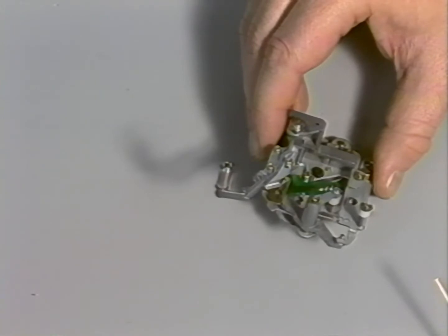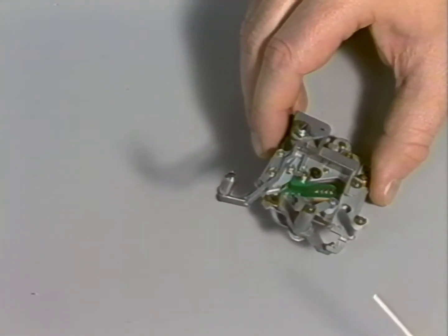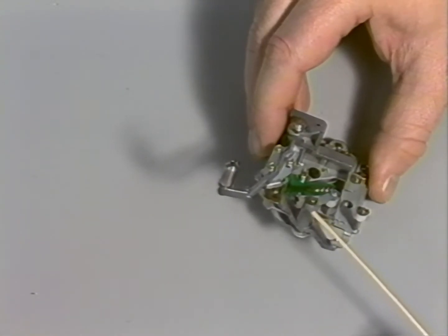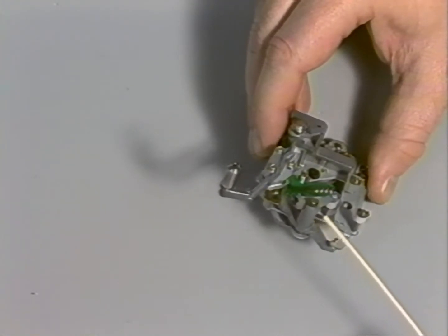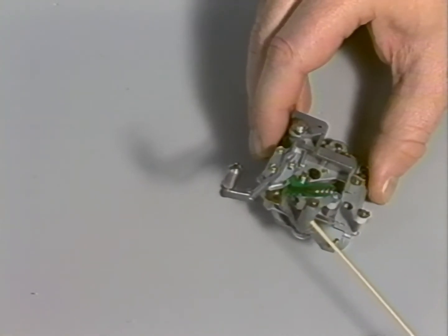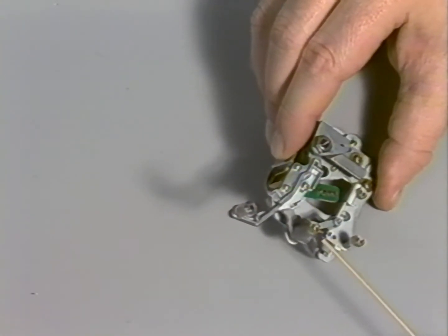The shaft that the return arm assembly sits on has been known to bind. If that's the case, that return arm assembly needs to be removed. The shaft needs to be cleaned thoroughly and relubricated. The process of removing that shaft involves removing the E-clip on top and the two small screws holding the brass leaf spring underneath the S-tension regulator arm.